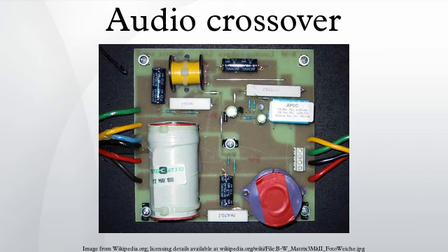It is commonly thought that there will always be a phase difference of 180 degrees between the outputs of a low-pass filter and a high-pass filter having the same crossover frequency. And so, in a two-way system, the high-pass section's output is usually connected to the high-frequency driver inverted, to correct for this phase problem. For passive systems, the tweeter is wired with opposite polarity to the woofer.